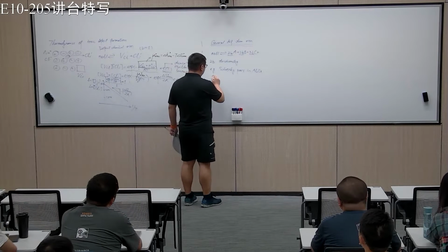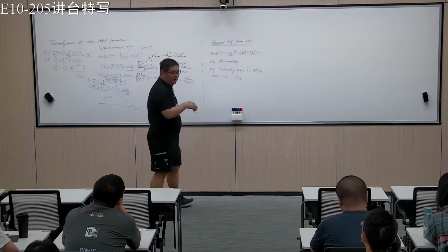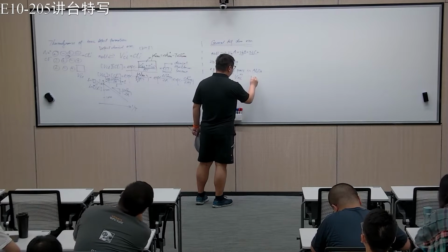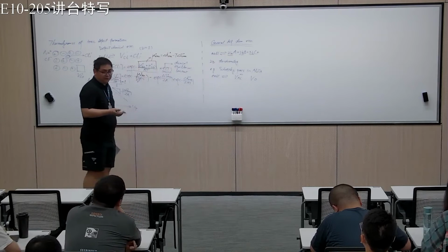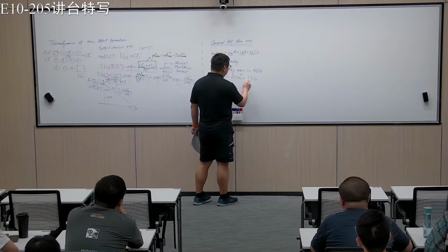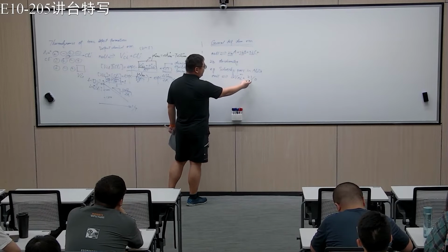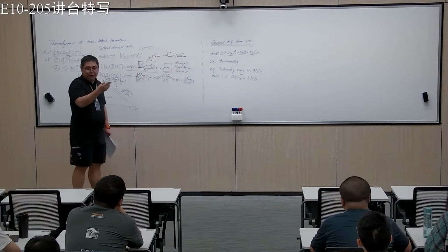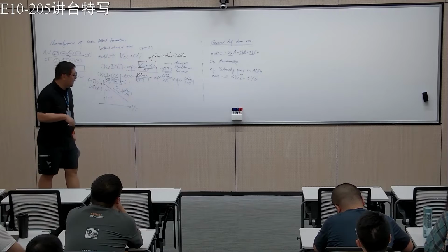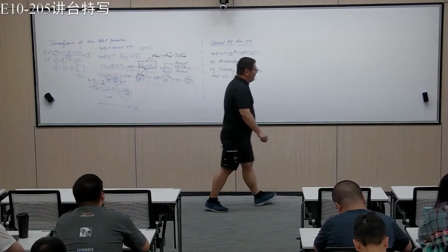We have to form an aluminum vacancy. Of course alumina has Al3+, so the vacancy has 3 negative charge. And oxygen vacancy, oxygen has 2 minus, right? However, you have to balance this, so you have to have 2 here and 3 here. So basically mu aluminum vacancy is 2, mu oxygen vacancy is 3. Anyway, you have to have this to balance the charge. Otherwise, the defect reaction is not correct.